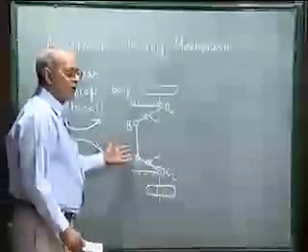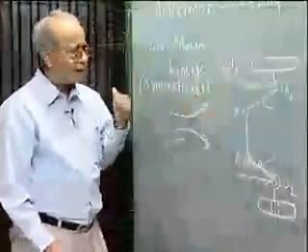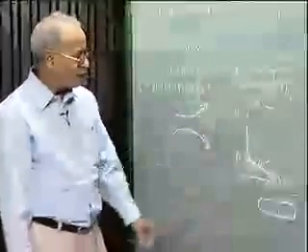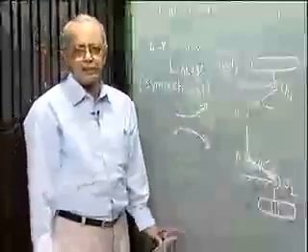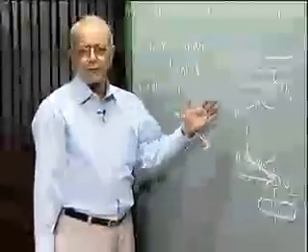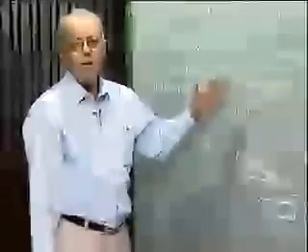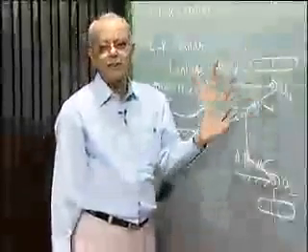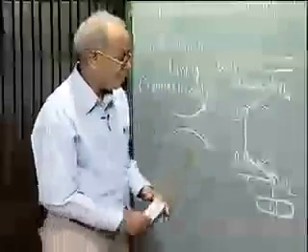Because it is simpler, we also have to pay a price, in the sense that the perfect steering condition cannot be maintained for all radii of curvature of the turns. The perfect steering condition can be met only at certain points, and we hope, if it is properly designed, that for other radii of curvature, the tendency of slight slip will not be too much.